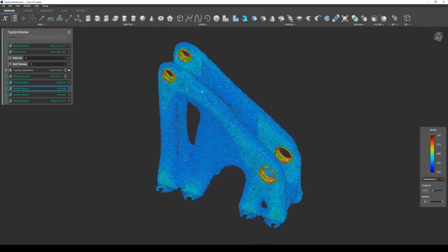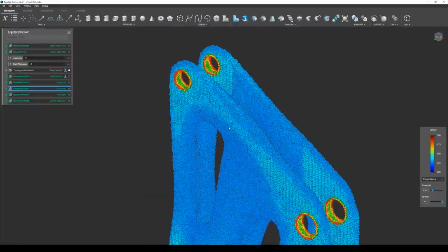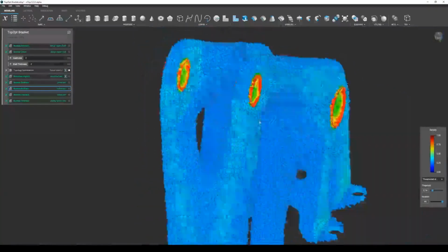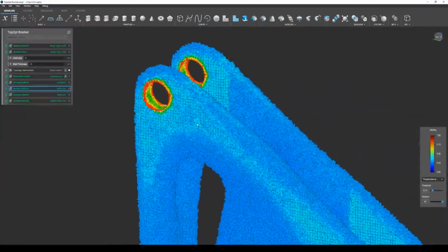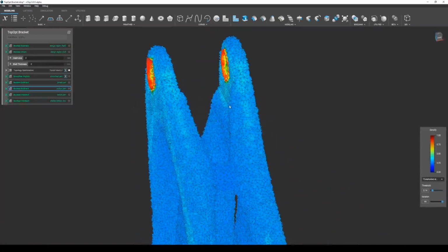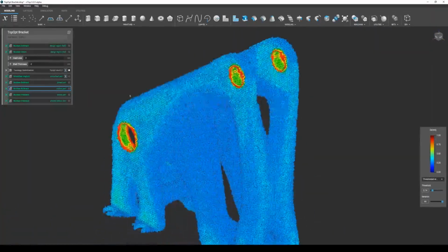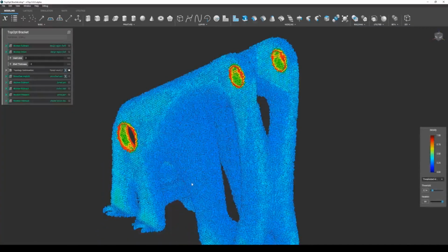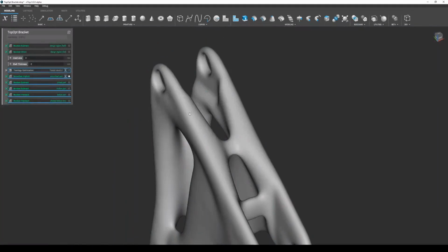Up to this point, this is topology optimization as many of you have seen or used before, but now comes the manual labor. What we don't want to see is engineers wasting their time clicking along a surface like this, or having to manually remodel bits after they get this nice organic-like design. Since what you see here is both a tet mesh and also a mathematical field in our software, we can just immediately fit a smooth geometry type to that.